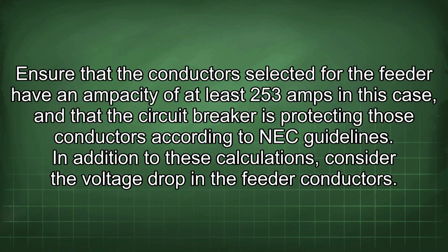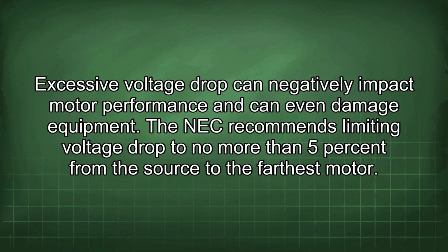In addition to these calculations, consider the voltage drop in the feeder conductors. Excessive voltage drop can negatively impact motor performance and can even damage equipment. The NEC recommends limiting voltage drop to no more than 5% from the source to the farthest motor.